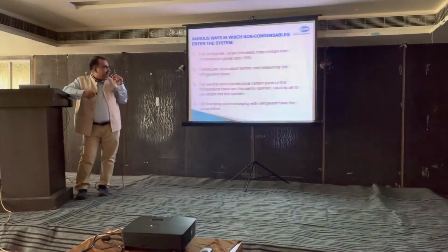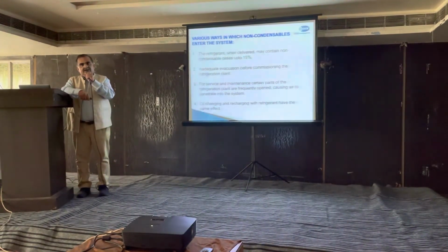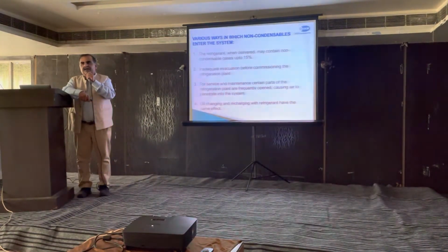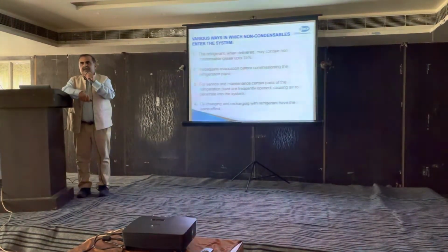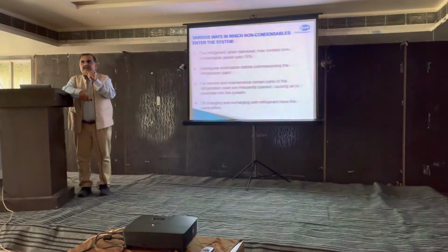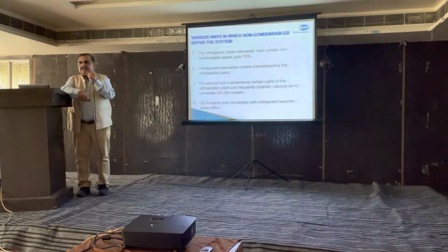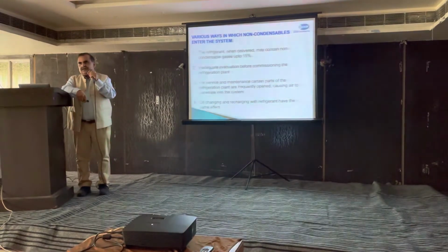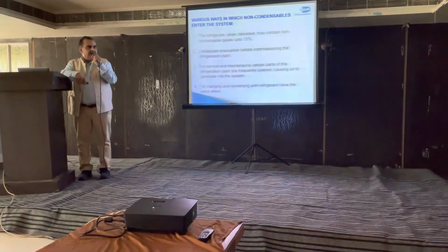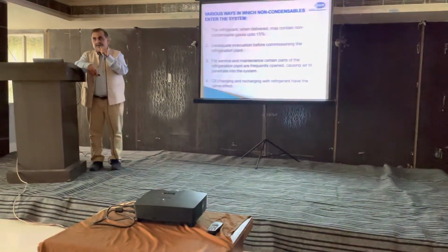Now air may come in when we get new ammonia. Ammonia cylinders may contain nitrogen or hydrogen and air itself. Because in India, when we are buying ammonia refrigerant, our suppliers do not provide us purity certificates. So there is no certification available of what kind of ammonia we are buying. So these cylinders definitely contain air and water. Remember, when you charge ammonia into the system, you always have this air also going into the system.